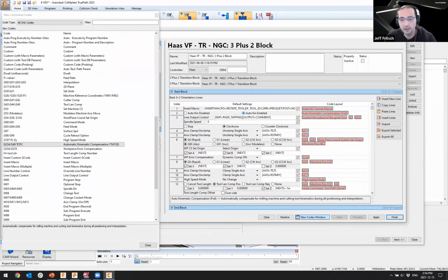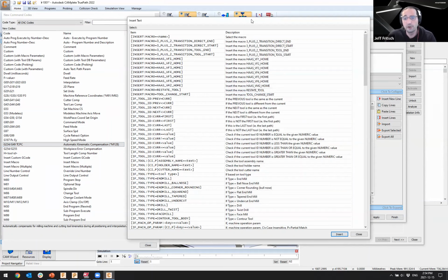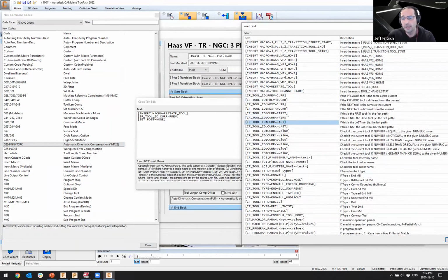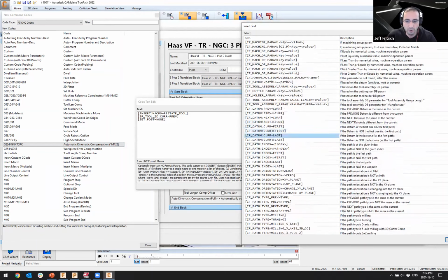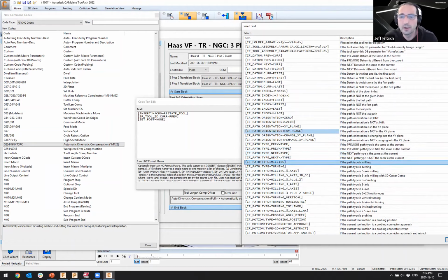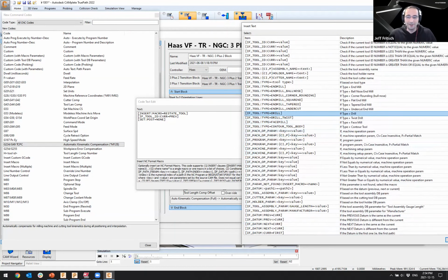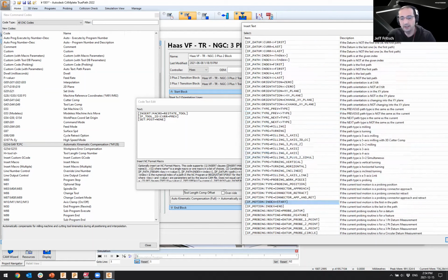And if you really wanted to dive very deep into it and start building macros and really control your process to a much greater extent, say, for instance, I would want to build tool breakage check macros after every drilling operation or tapping operation. So if my tool is a drill, then I would put the tool breakage check. If not, then I would put something else. If I'm doing probing, and this output comes out.